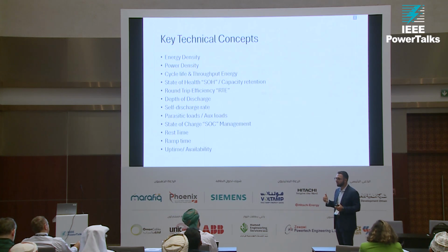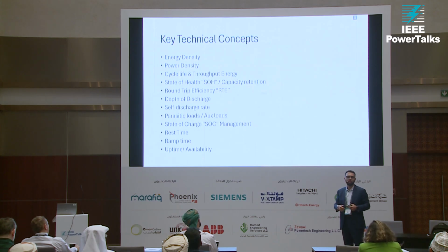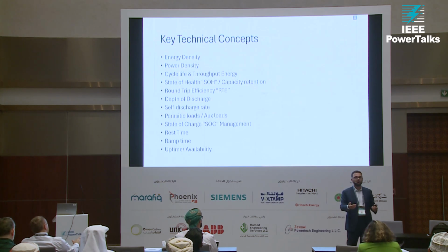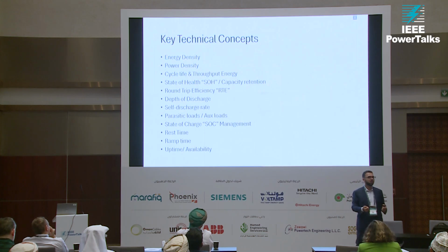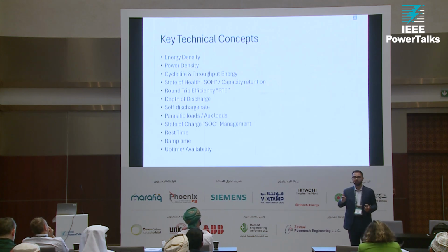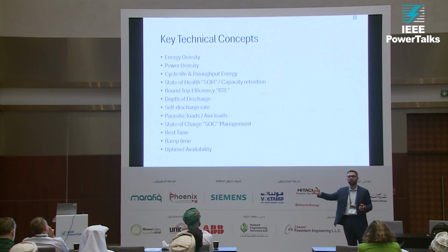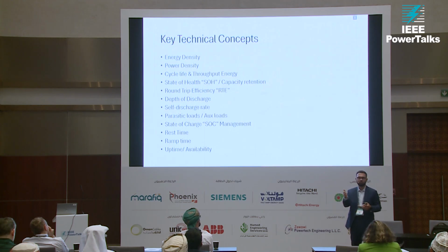So state of charge management becomes very critical when you work with multi-megawatt-hour systems, because as a system operator, you don't want to find out about your state of charge, or how many megawatt hours you have in your battery, on the 11th hour. You want to have that planned because you want to know how to manage it in case you have to discontinue a charge cycle and jump to a discharge cycle.